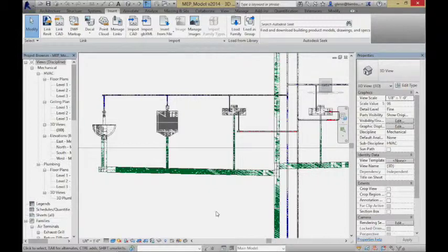In a sanitary system, a 4-inch pipe is so big that it'll be big enough to handle all the projected loads, because unless we were all flushing all the toilets continuously at exactly the same time, there's this offsetting. Very few times do you actually have all the loads contributing at exactly the same time. So usually a 4-inch pipe will take care of these things.